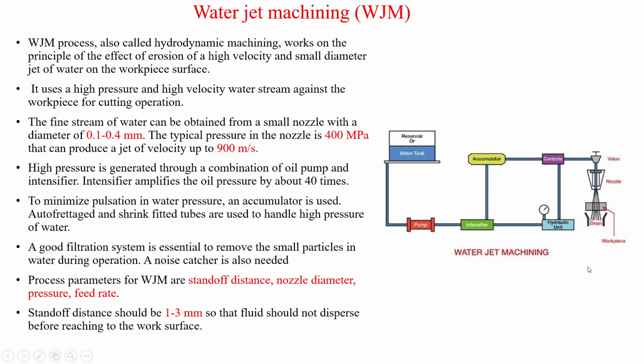Finishing, which is the water jet machining. So this is similar to the abrasive jet machining, but instead of the abrasives, here water is used for removing the material, because water is being pushed into the material at a very high speed, so that water removes the material. This is the water jet machining. Rest the process is the same only.